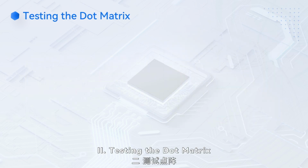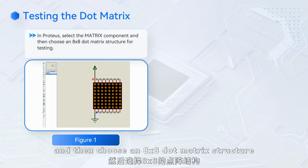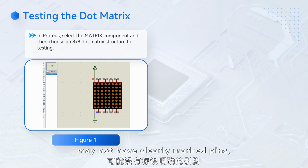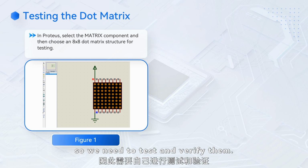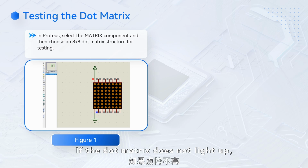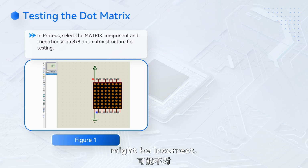3. Testing the dot matrix. In Proteus, select the matrix component and then choose an 8x8 dot matrix structure for testing. Note that the dot matrix in Proteus may not have clearly marked pins, so we need to test and verify them. First, connect a power source and try it out. If the dot matrix does not light up, it indicates that the polarity of the power connection might be incorrect.